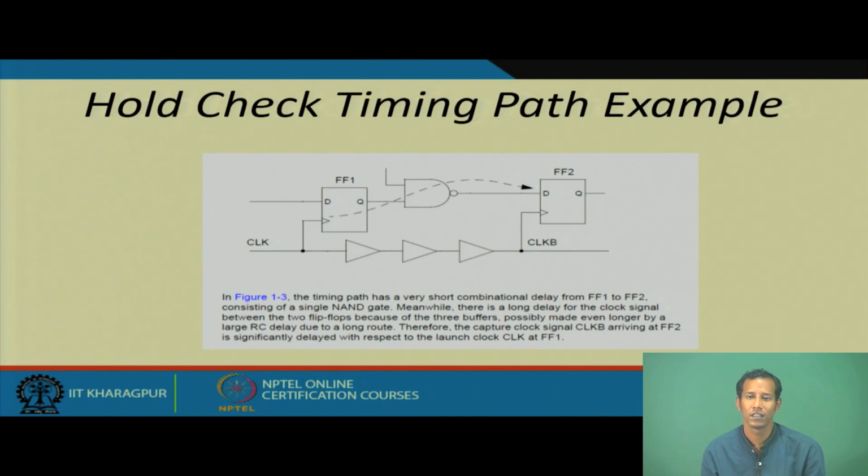In clock tree synthesis, if this is the location of the clock pin, the path traversed to reach this flip flop and the path needed to reach the clock pin of this other register are not the same. So there will be a delay difference between the two clocks. To increase the strength of the clock, we put some buffers on the clock tree path, so that every sequential element on the digital IC gets clock signals of the same strength.